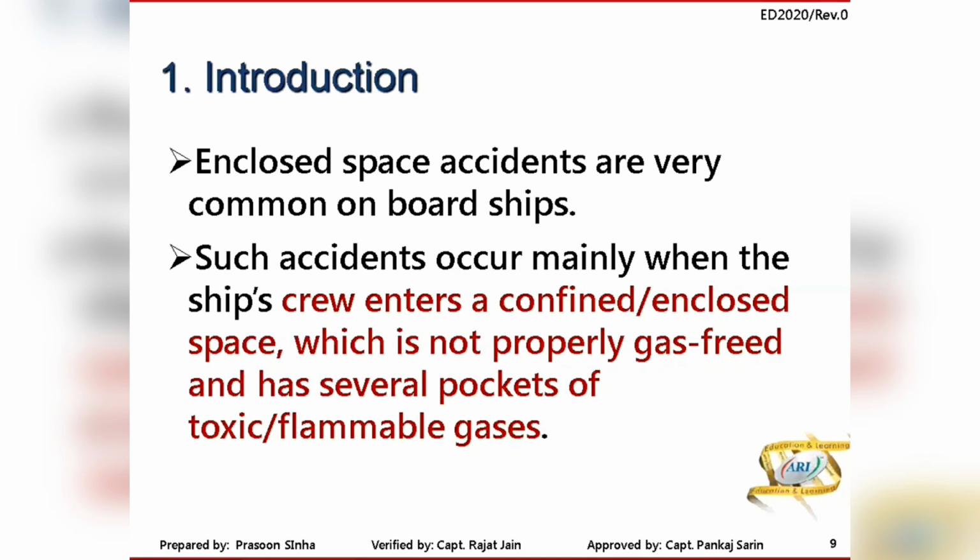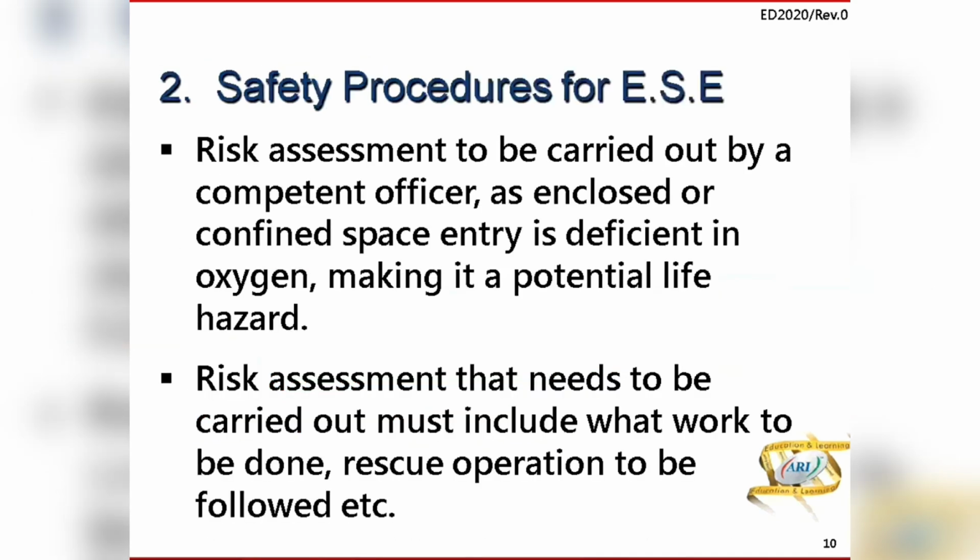There have been a lot of accidents in enclosed spaces. This occurs whenever ship crew enters a confined space which is not properly gas free and has several pockets of toxic, flammable gases. A risk assessment has to be done by a competent officer, as confined spaces are deficient in oxygen. Therefore, it is a life hazard. The risk assessment should consider what kind of work has to be done, rescue operations, etc.